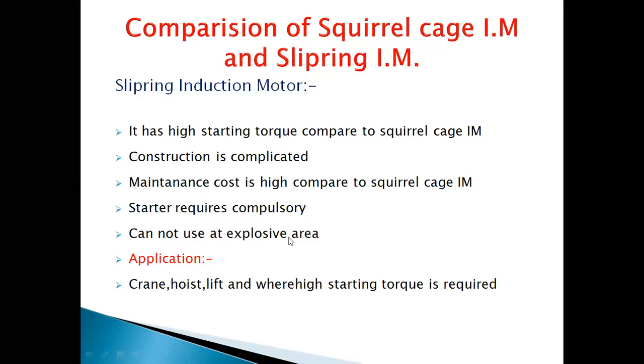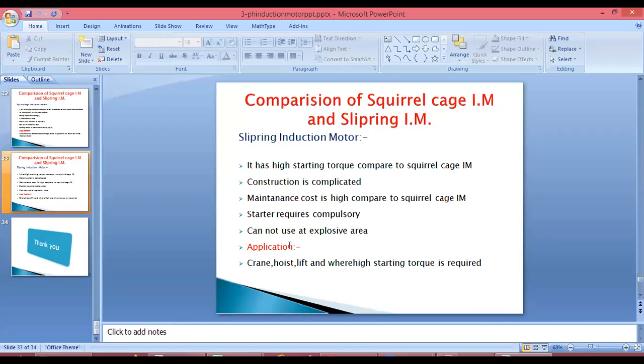And if we will talk about its application, you can take the applications as crane, hoist, lift, where we will require higher starting torque. So we can use there slip ring induction motor.